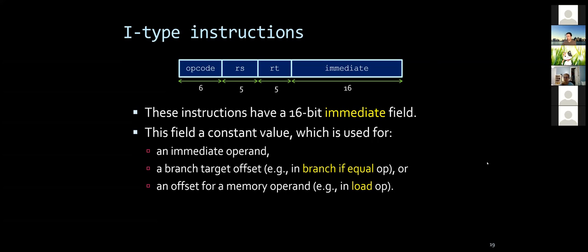Ivy asked how I knew that it was XOR. I know it was XOR based on the function, right? The last 6 bits of the instruction tell me that's the XOR instruction. I had a table. Remember, I showed you the table at some point. That table tells me which function it is, one of the yellow instructions.